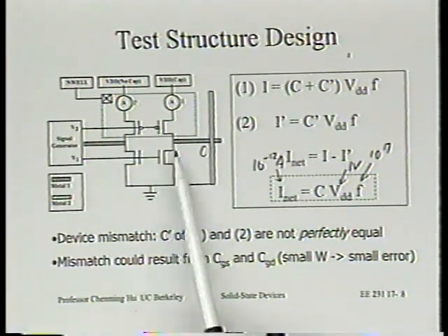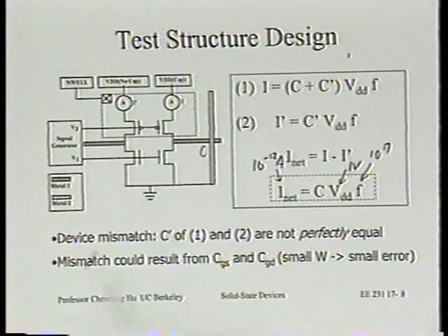So it's a mismatch. What you do is you try to use a transistor that's not very large. You don't need a large W because you won't have to be fast, right? So it's kind of close to minimum. You don't want minimum either, because at very minimum, maybe the mismatch is a little larger, right? So the mismatch of the transistor parasitic capacitance is probably a small fraction of the transistor capacitance, maybe 1/100th of it. So is that resolution good enough or not?